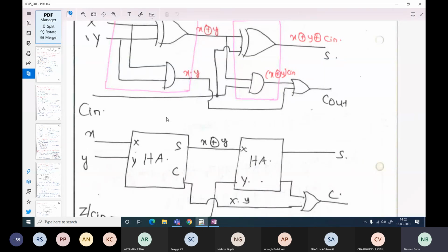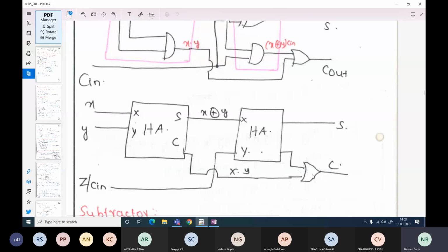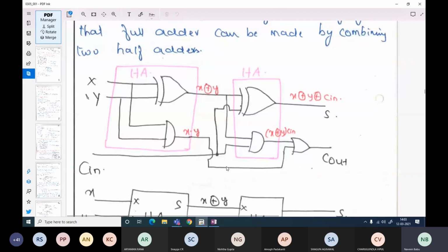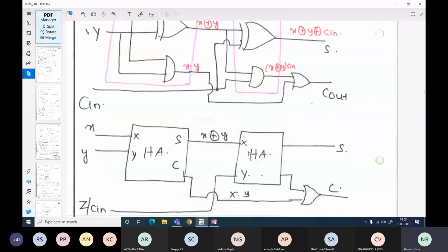So you can purchase one single half adder IC and, in this particular case, an OR gate IC, and create a full adder circuit. If you go for a gate level design, then you have to purchase different kinds of ICs: an XOR gate IC, an AND gate IC and an OR gate IC. Which means three different types of ICs.